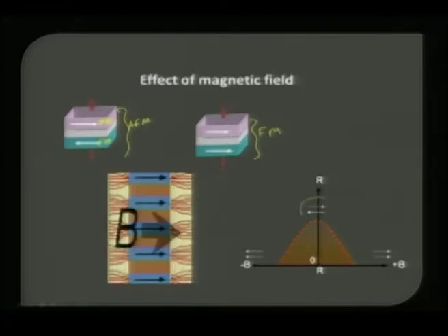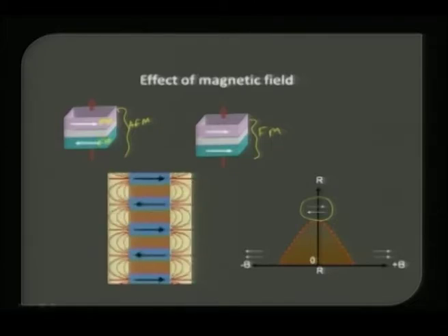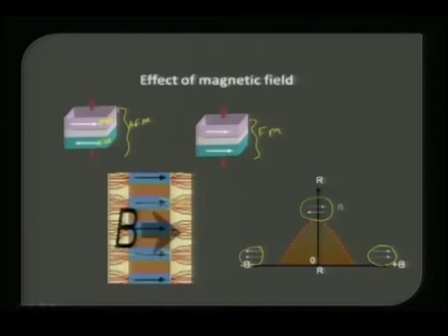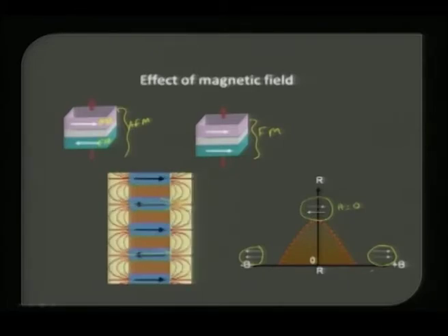That is what we show here. But once you force with the magnetic field in this direction, all these anti-ferromagnetically coupled layers also go ferromagnetic. As a result, you have a low resistance state and a high resistance state at H equal to 0, which is important for the magnetoresistive property.